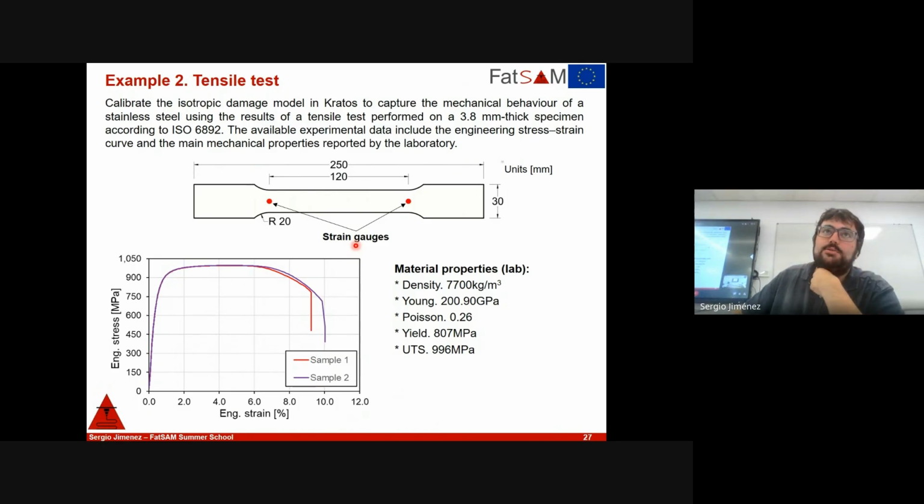And what I'm giving you, this IGS file, is just a geometry file that I've created using AutoCAD. And in that, I created the sufficient divisions in order to be able to detect or to position these points here. I'm giving you just a quarter of the sample. It's up to you if you want to run a quarter, a half, the full geometry.